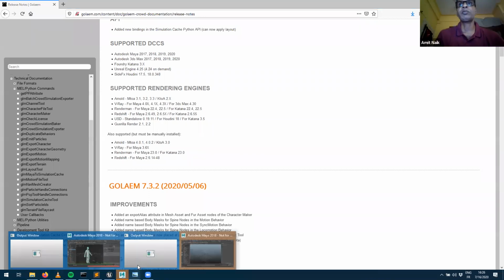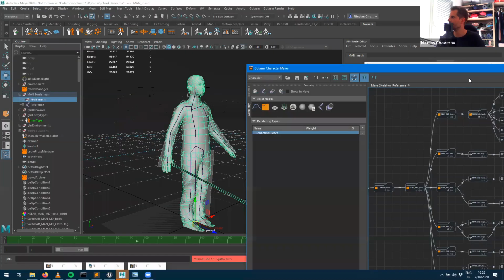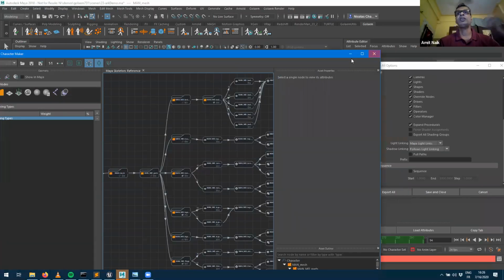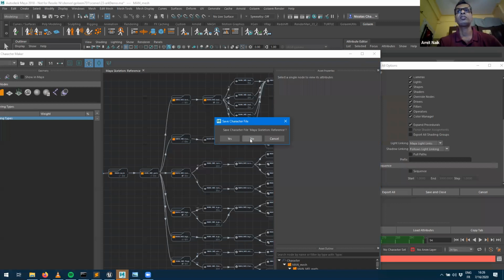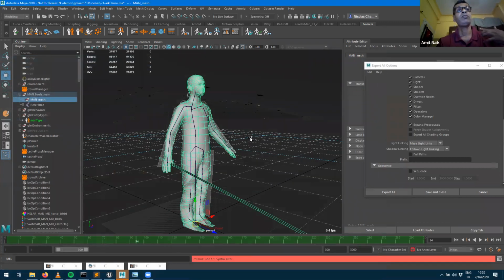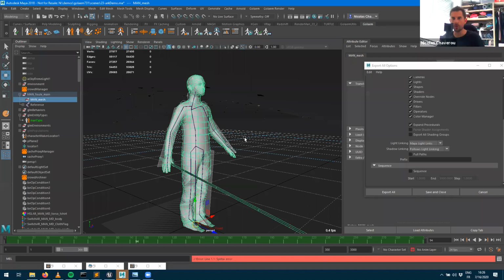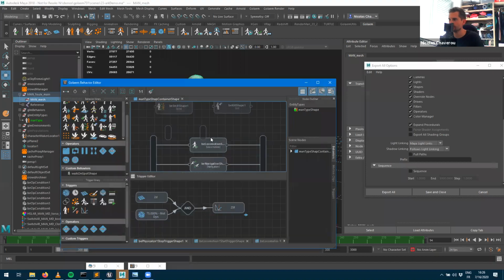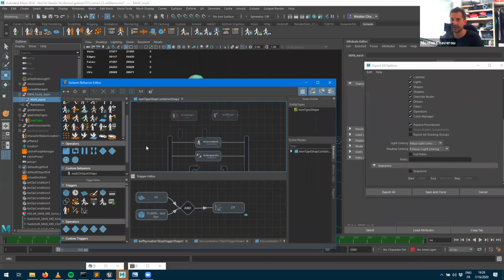Now, I think this is the last question of the day. Great. What should I do if I want to direct a few characters to move through obstacles manually? Meaning he wants the characters to move through the obstacles, and how do you control a few particular characters to direct them towards a particular object? True. That's something you can do with the go-to target. The go-to behavior, you can just use that on a separate set of characters. You can select a bunch of characters and say, I want to assign a trigger to those guys, and this is going to be their target.